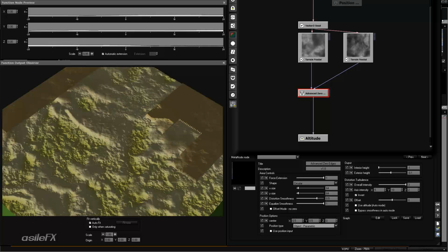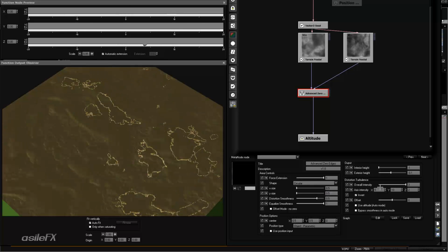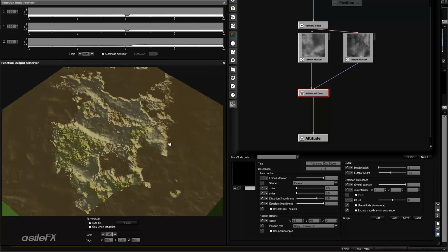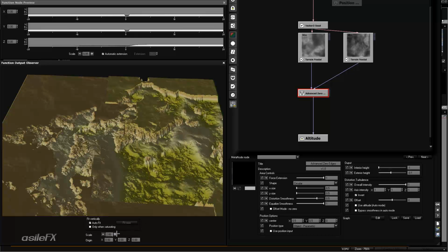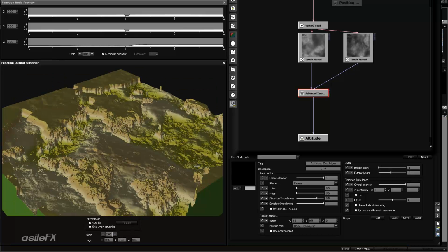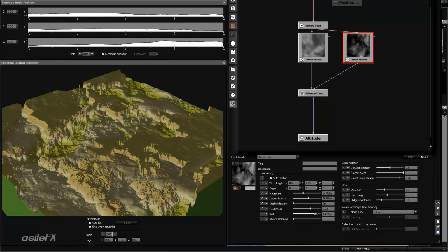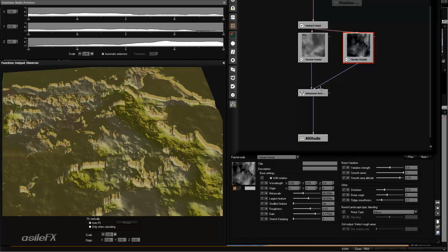I'm going to go ahead and switch this back to the object parametric mode and reset those axis intensities to 1, overall intensity to 1. Now if you take a look, our edges are getting rather sharply cut off. This is because of the distortion smoothness, and because I have the gain set a little higher. The higher the gain output of the controlling distortion, the sharper the cutoff is going to be.